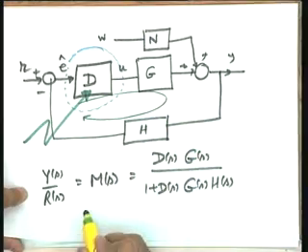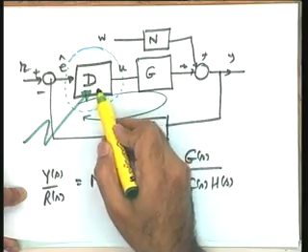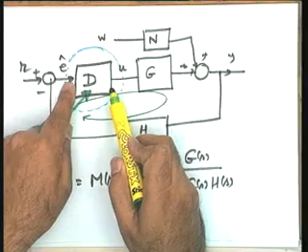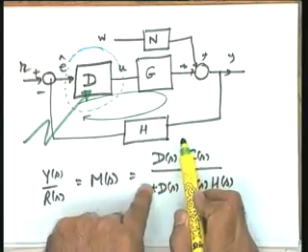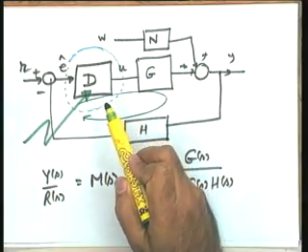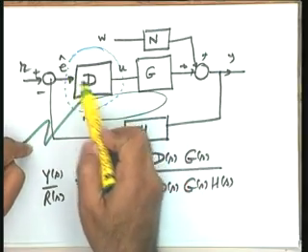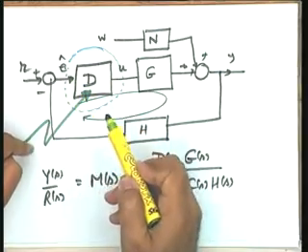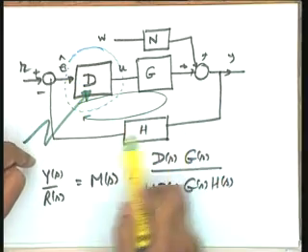And 2 of the things which we will be taking up are the derivative action and the integral action. So you see now the need of derivative action and integral action. Your amplifier gain here, only amplifier gain, may not satisfy all the requirements. You have to look for alternative Ds, and a couple of suggestions are that in addition to the amplification, you take the derivative of E, and you take the integral of E and inject that particular signal in the loop.